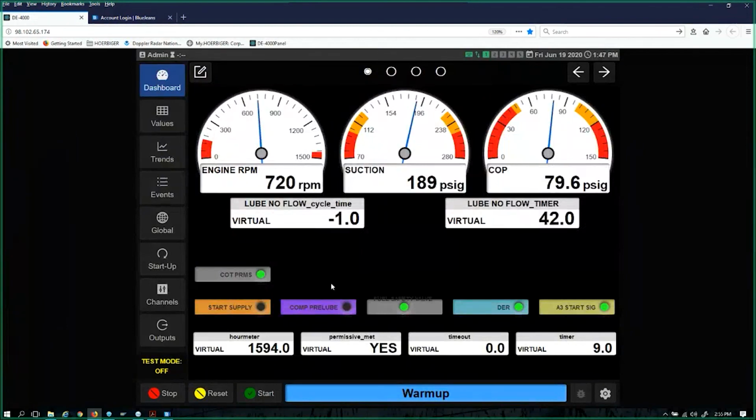In my case, what I do in a lot of my applications is I turn it on at the beginning of the prelube state, and once I've met my parameters, I keep it running until I need to turn it off. It just turned off about the time you were asking your question. I don't turn it off until the RPM is greater than 300 RPM.